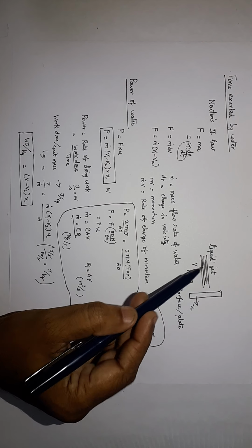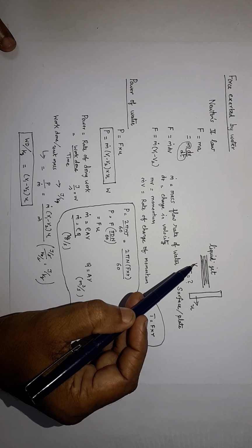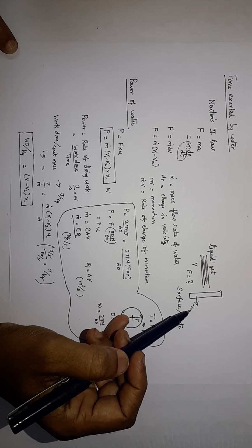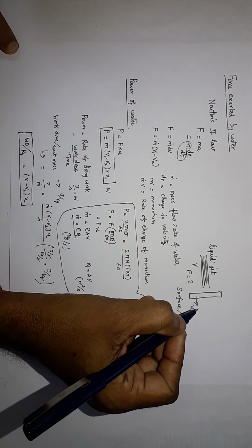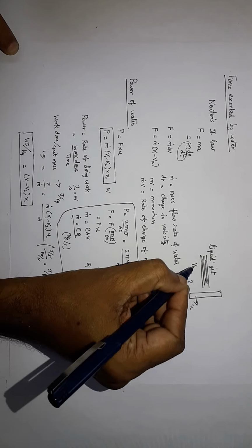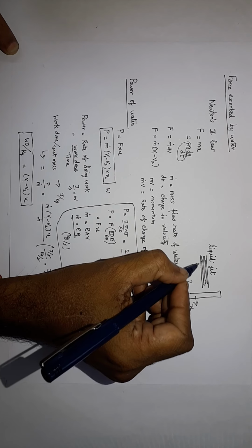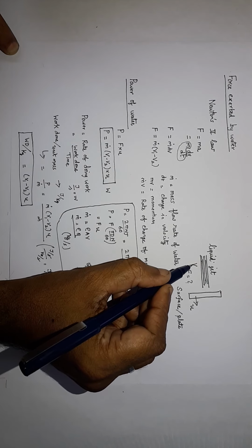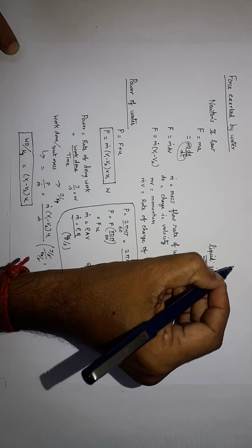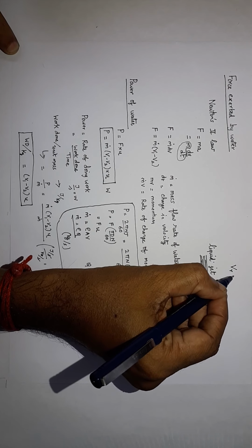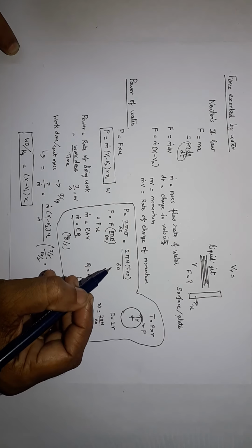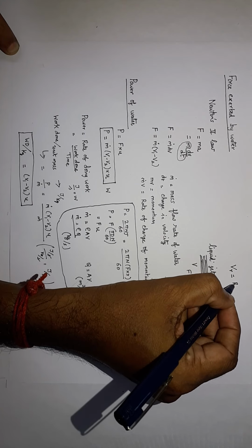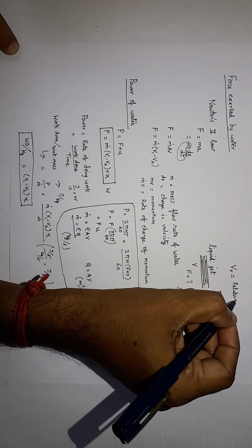This concept is very important. So v is the absolute velocity and u is the absolute velocity of the plate. So here you can write one more thing, the relation between these two. The water is moving with velocity v and the plate is moving with velocity u, then there will be some relative velocity between the water jet and the plate, vr.